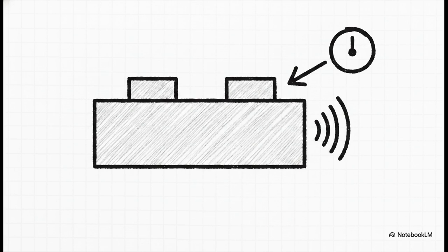Now, brute power isn't the only challenge in electronics. Speed and frequency are just as critical. Standard FETs suffer from high input capacitance because of that gate structure we just talked about, heavily restricting their use at higher radio frequencies. The solution?